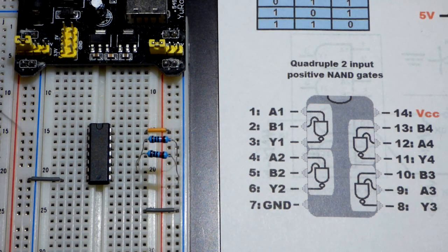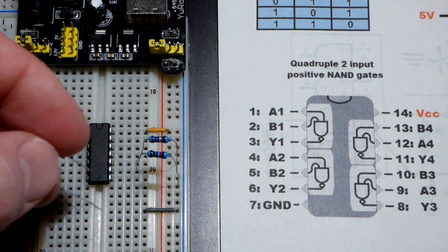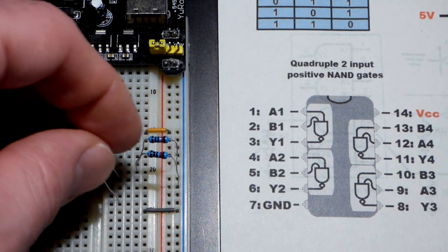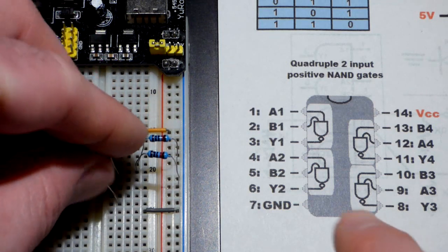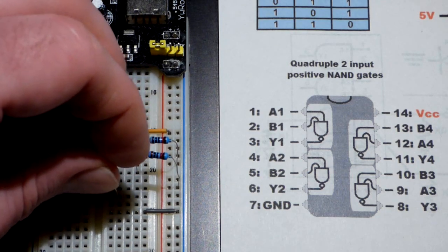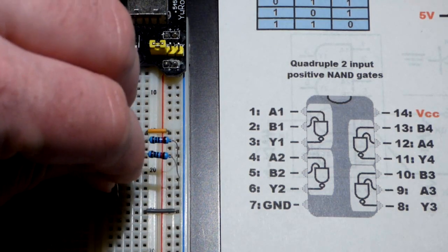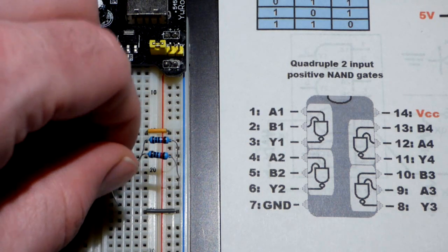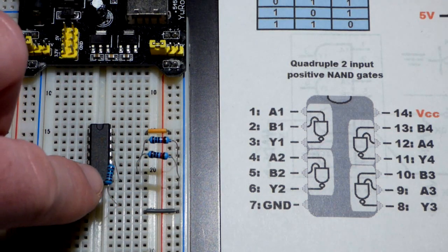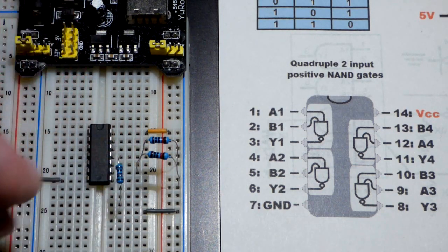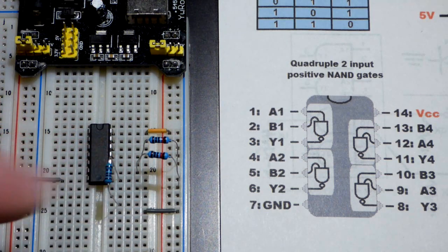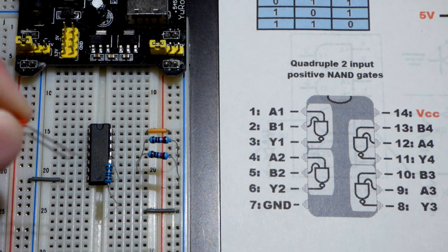Let's attach our load. So I got a jumper down there, so I'll use a 1 kilo ohm resistor, 1000 ohm resistor, and that's because this is not intended to output much current. I think you're only supposed to output about 4 milliamps of current. And so if you need more current, output this to a transistor and use this to turn the transistor on and off and let the transistor handle the rest of the power. But that's a topic for a different video. We're going to stick with a really light load in this video.